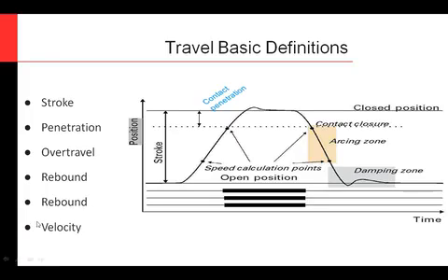One thing I'll mention here is velocity. Velocity is very important. Why you want to measure velocity is you might have a circuit breaker that maybe the trip coil is bad or something's wrong with the coil. So it might operate slow. Instead of operating in 20 milliseconds, it might take 50, 100 or something because it's bound up.